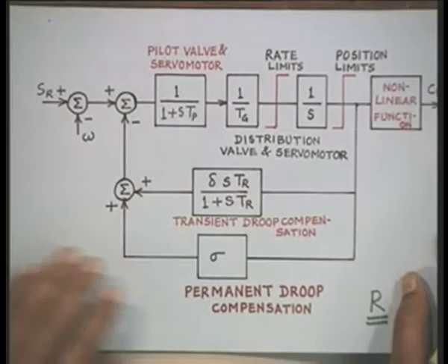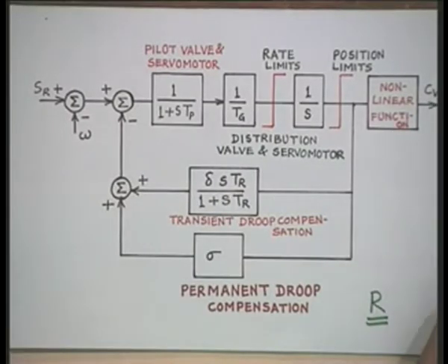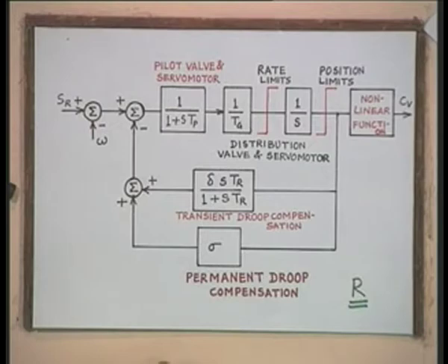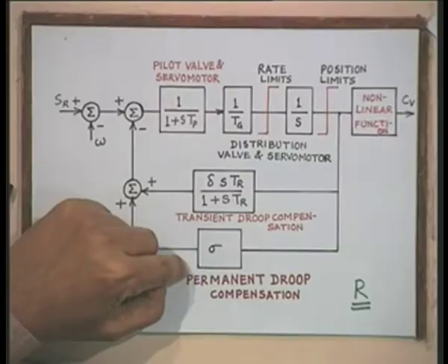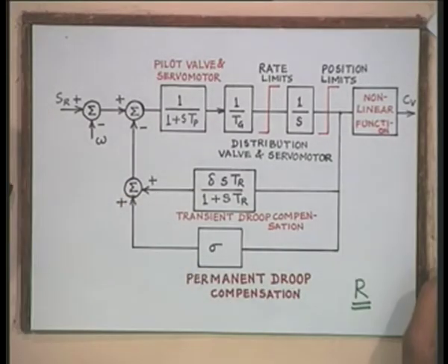However, in any particular system, the procedure is that you model the complete system, like the hydro turbine, take its associated governor, and you obtain the dynamic response of this system, and we can use different techniques to set the parameters of these governors, right. Generally the governor parameters are set under no load conditions.